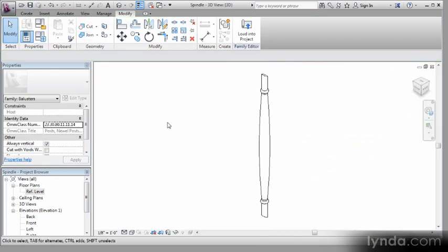It's not a bad spindle. Notice all the procedures for creating these families are always the same. As you can see, we're gaining a lot of control over the aesthetics of our stairs. By starting with the right template, then adding reference planes, parameters, revolves, and voids, we have a spindle that can go on any staircase.